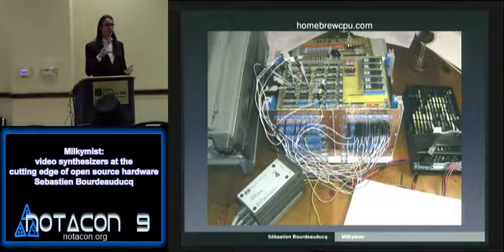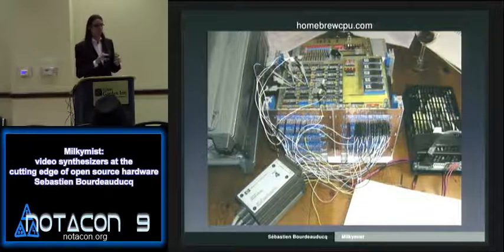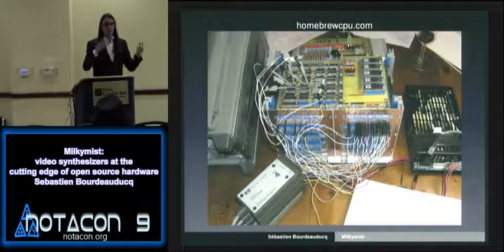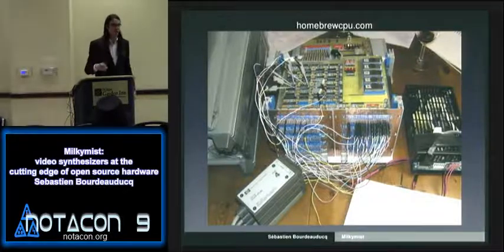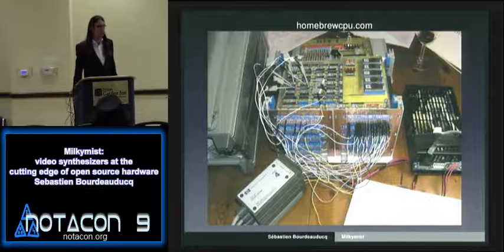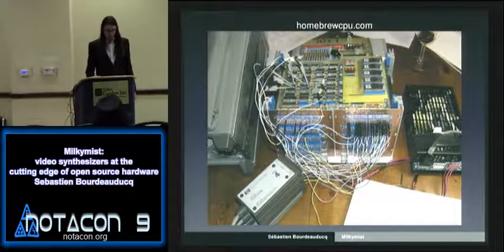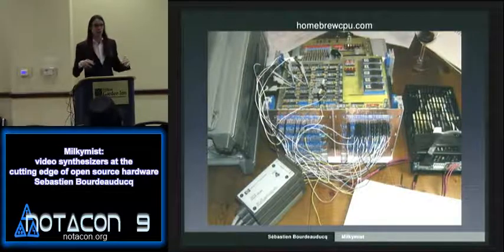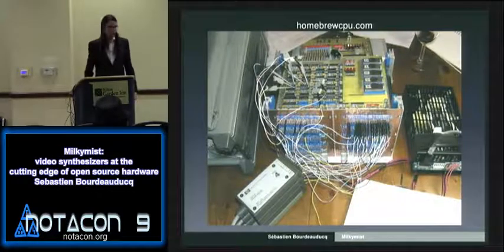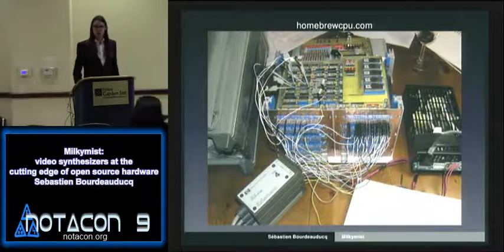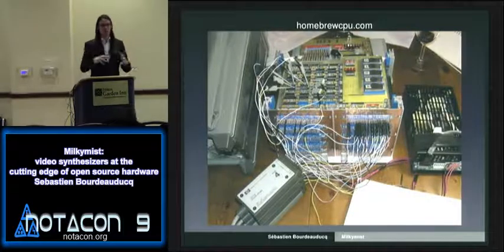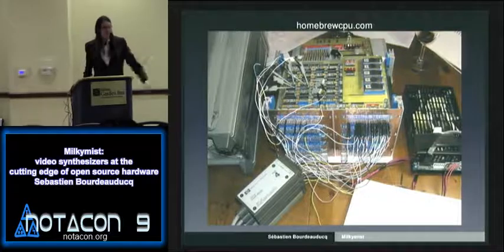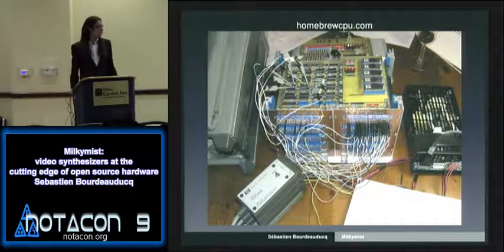CMOS chips come with various sets of logic gates, so you need to optimize. One chip can serve different functionality of the CPU because, let's say, you have a chip which has 8 AND gates in it, and of course you want to distribute these AND gates in different parts of the CPU, so you have to do that manually. Then you have to find a layout for the chips, and then you have to connect all the wires together, and it creates one big mess like that. So if we were to design the Milkymist system on chip using such a technique, which is possible, it would really require a lot of manual work. It would probably be a machine the size of this table, and it would be pretty slow because you have all these delays over routing in the different wires.